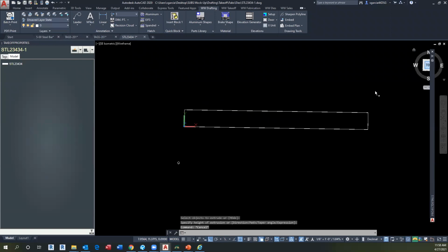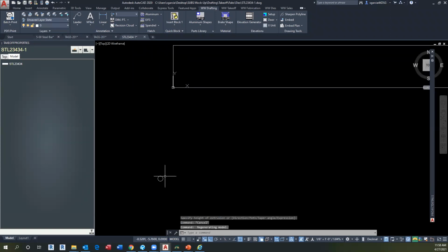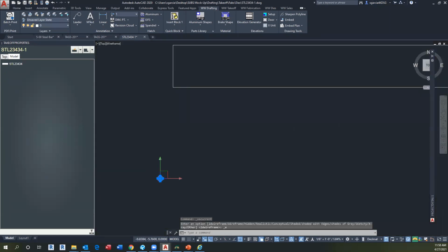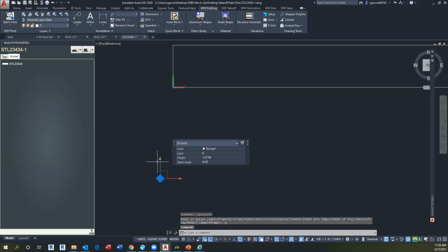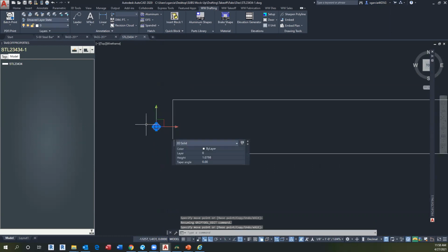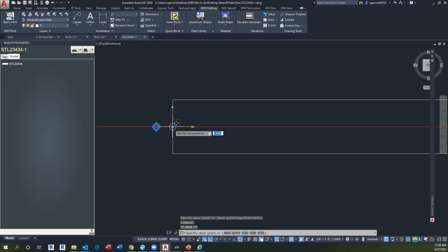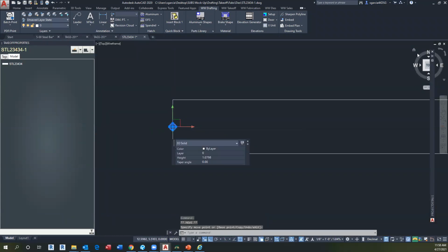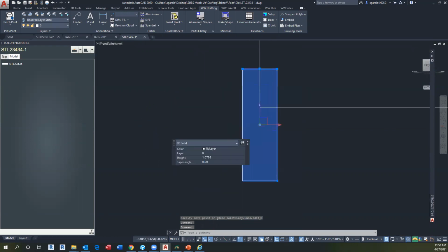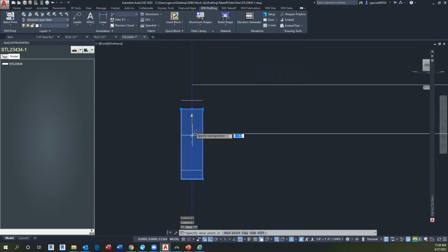So now the only thing I need to do is place it in the right position. If I go here to the wireframe, I can use the arrows, and it's just more accurate. So I go here to the center. I know it's in the center, and I center there. So now I have it in the right position on X and Y, and I use C and just center it on that particular dimension. There you go.